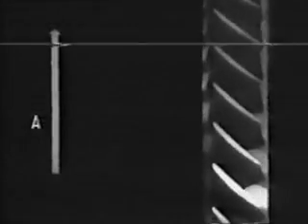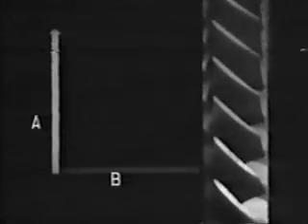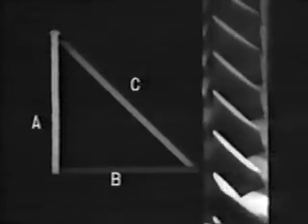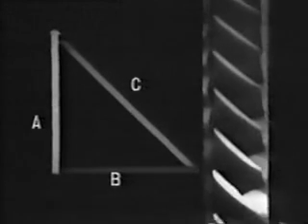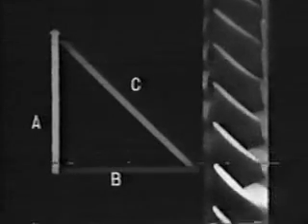Using vector diagrams, here's the direction and speed of the forward stage rotor blade. We'll call this vector A. And here is the incoming air. Vector B shows its direction and speed. The resulting angle of air meeting the rotor is vector C. This, of course, is the ideal situation, where air meets the blade at the angle the blade is designed for.